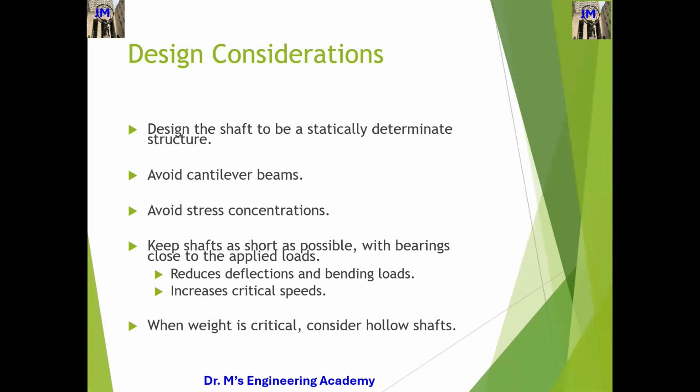So usually you know the frequency at which the shaft is rotating, and then you need to know the natural frequency, which is related to the geometry and the material, right? So you need to do the natural frequency analysis to make sure your operating frequency of the shaft is far away from the natural frequency. Otherwise, resonance can cause big trouble. You know resonance, right?